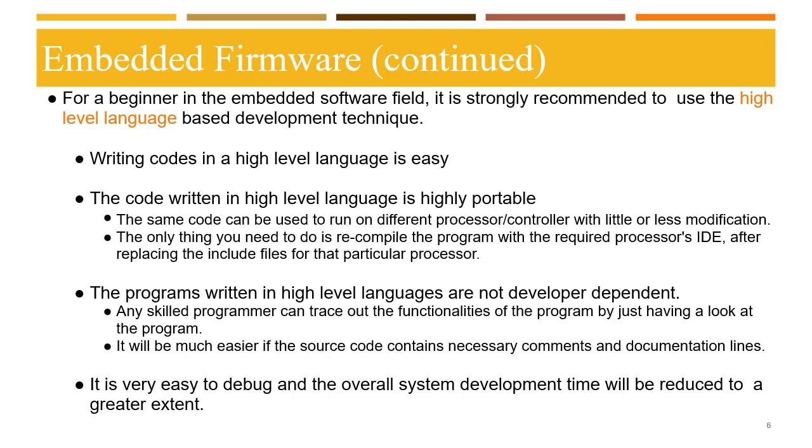With little modification, the same code can be run on different processors or controllers. The only thing you need to do is recompile the program with the required processor's IDE after replacing the include files for that particular processor.